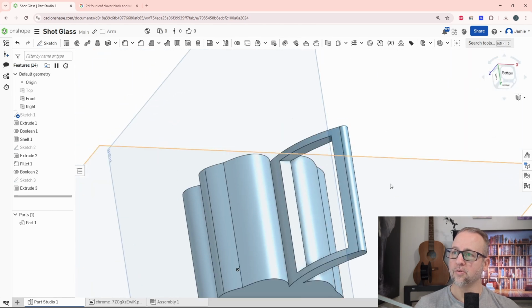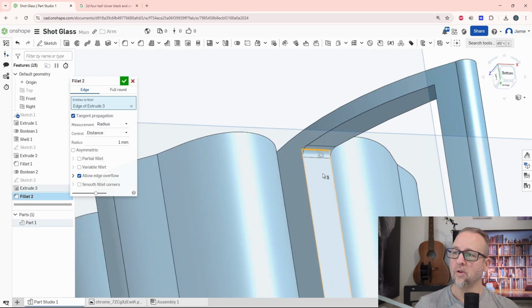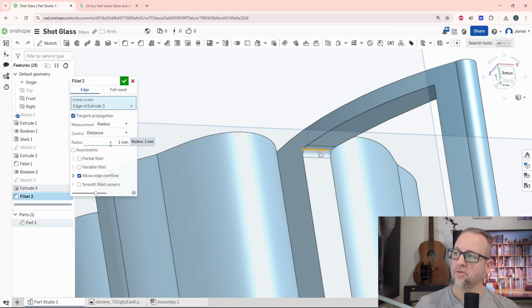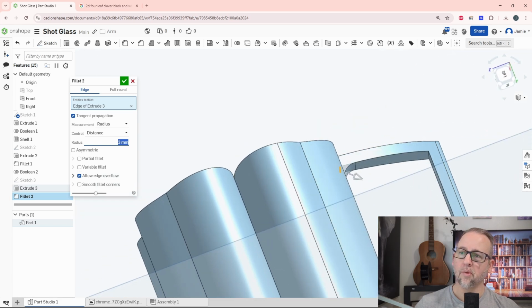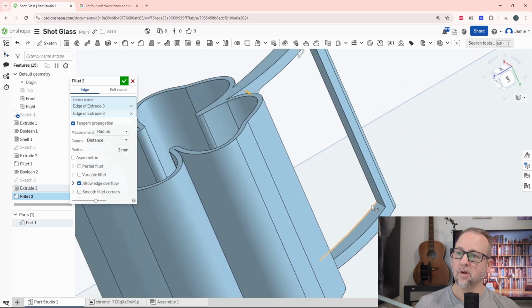Now we'll put some nice radii on here. Let's grab some radius. This will be an easy breaking point, so let's make this pretty big. Let me go back and fix that fillet. I wanted, let's do 3. I think that's probably okay. You know what, I'm going to make this thicker too. This doesn't have to be this big.